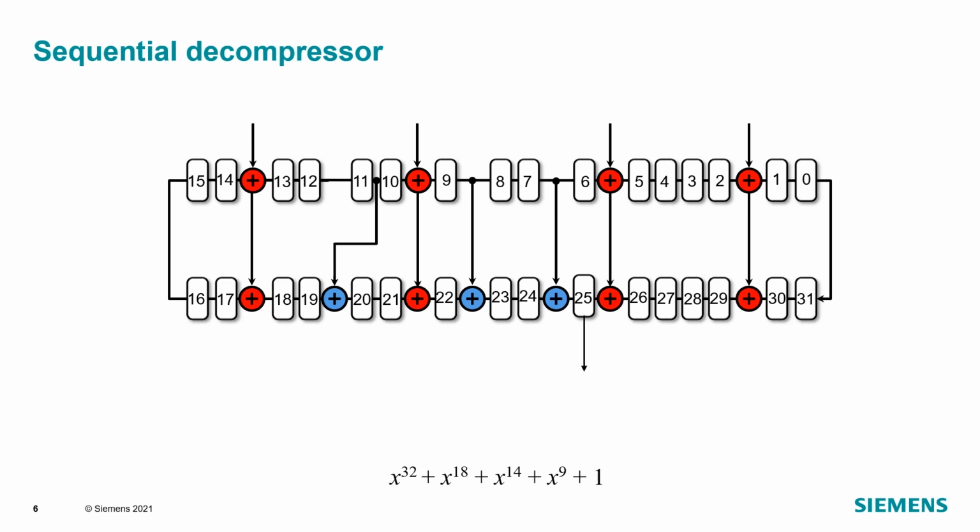The injectors, through XOR gates, provide the compressed stimuli. The phase shifter distributes decompressed stimuli to a large number of scan chains. Each output of the phase shifter is controlled by a 3-input XOR gate driven by 3 different flip-flops. Its role is to drive a large number of scan chains while minimizing linear dependencies between its output streams. This way, a high encoding capacity and efficiency is achieved with reduced area overhead.